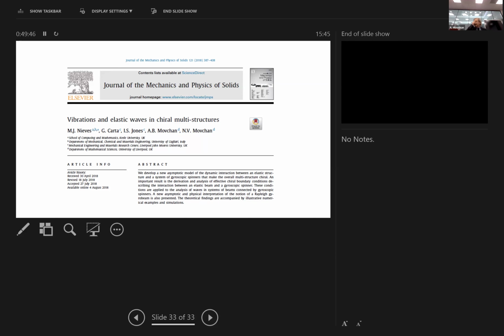But for example, if you look at the way helicopters are operated, the helicopter blades, when you put them together, can be considered as a gyroscope. And when they start the engine, they really want to pass the regime corresponding to low resonance frequency very, very quickly. And when they shut it down, they have dampers. And these dampers are essential. If these dampers are out of order, the helicopter may be damaged.